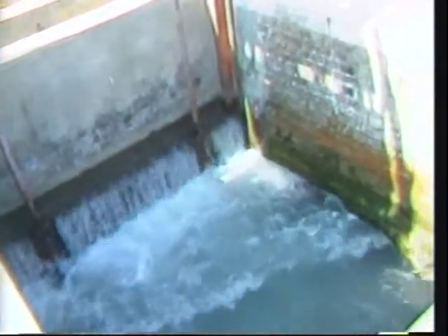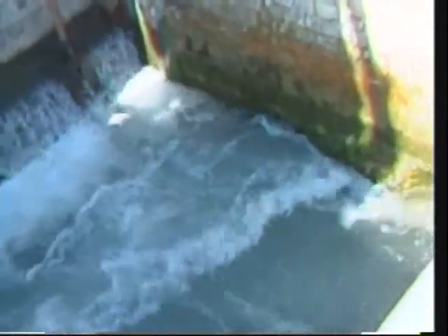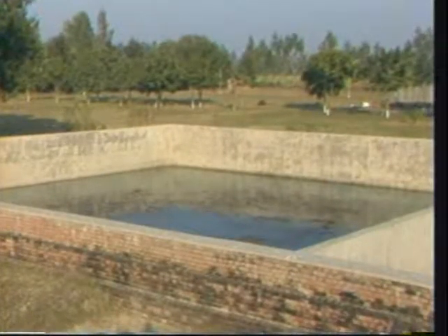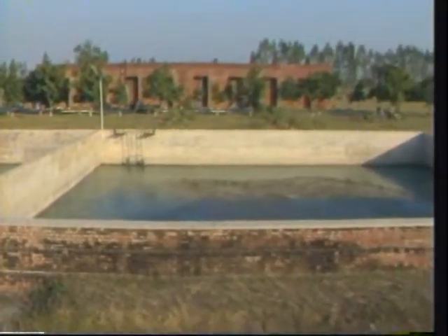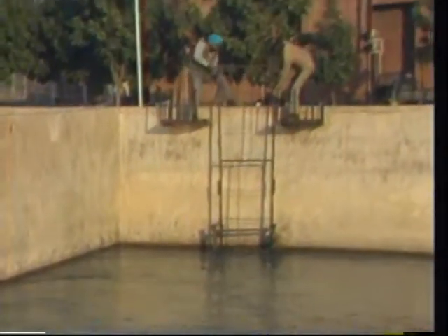The flow of water is regulated by movement of the gates. This water is carried through pipes or open channels to the suction tank. At the suction tank, larger size suspended matter is retained on the screens provided at the outlet, thus allowing only the screened water to reach the pump house.